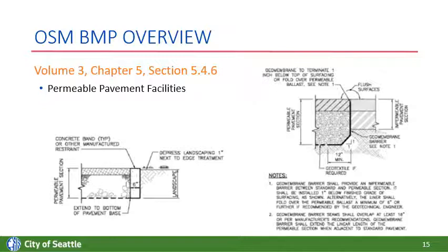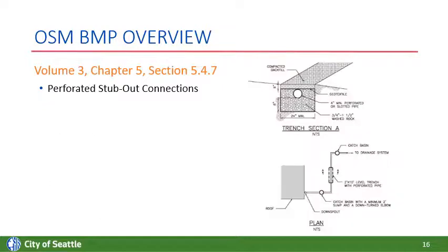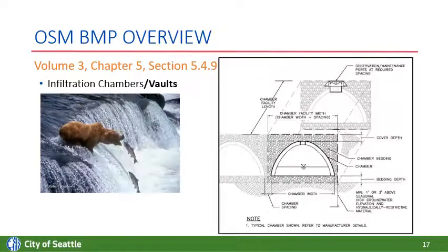These are provided as possible edge treatments, but the city will also allow other options, including potentially proprietary options as well for edge treatments. For perforated stub-out conditions, the figure has been updated, and it's been clarified if an overflow is to be eliminated.